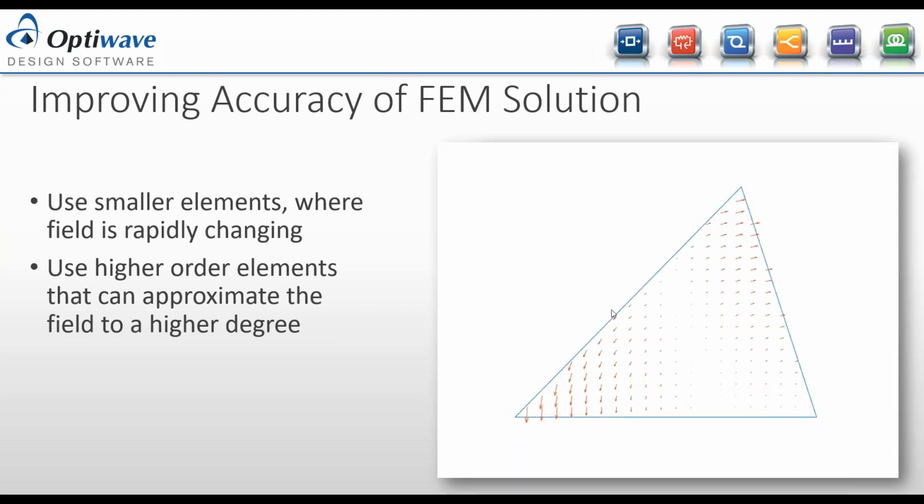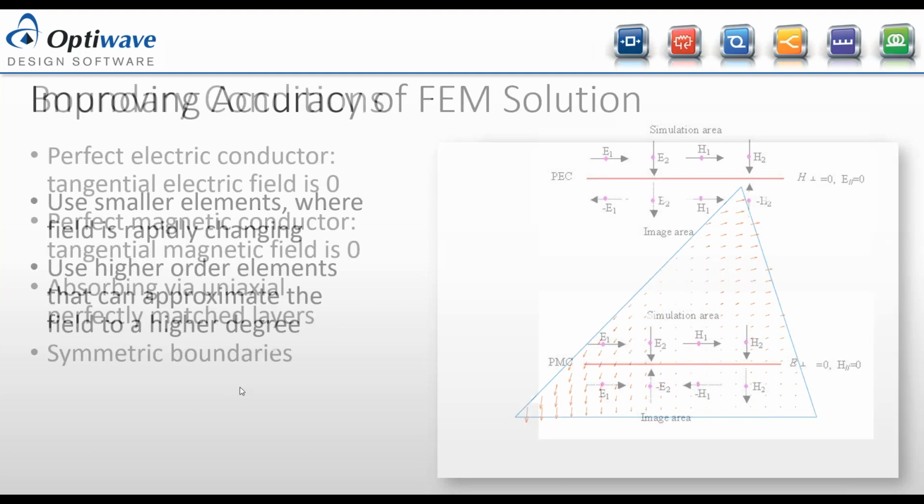And here's one. It is, I believe, a quadratic basis function. It has another sort of 0 node on the top edge over here. However, it does decay to 0 at the opposite node. This is the basis function associated with this edge at the top left. So that's important. The 2 ways to improve accuracy are using smaller elements or using higher order elements. Personally, through a lot of my own practice and going through literature, I've found that using cubic order elements is a very good starting point. It provides a high level of accuracy.